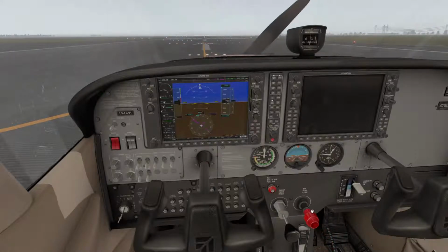We're going to set 113.9 here. And then from Dolphin, we know our next waypoint is going to be 117.4. So I'm going to put that in the standby. So 117.4. And green, the light means it's active. So I'm actively trying to tune Dolphin, and I'm actively trying to tune Uniform Charlie Alpha, which is a little ways away. We probably won't get it, 117.4. But then in the backup here, I'm also going to put 117.4. And then after 117.4, I'm eventually going to be looking for Sangster, which is 115.7. So I'm going to set that over here in that standby.